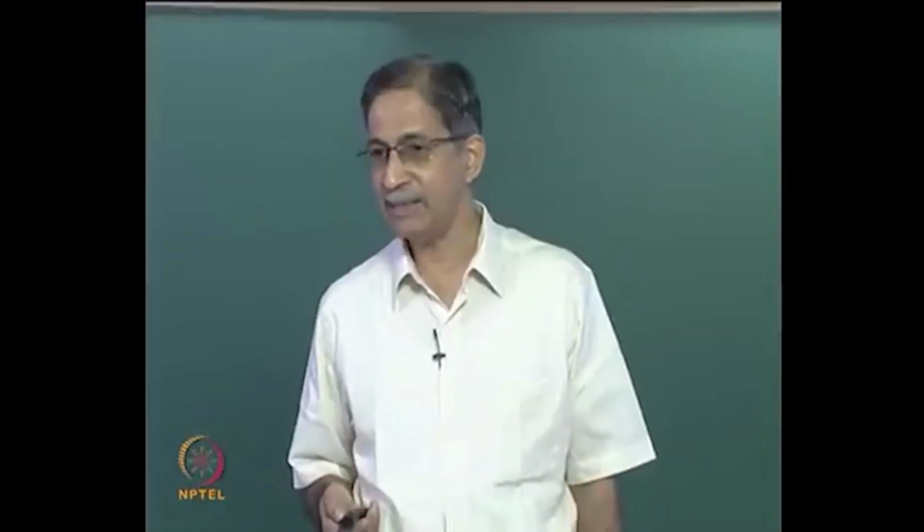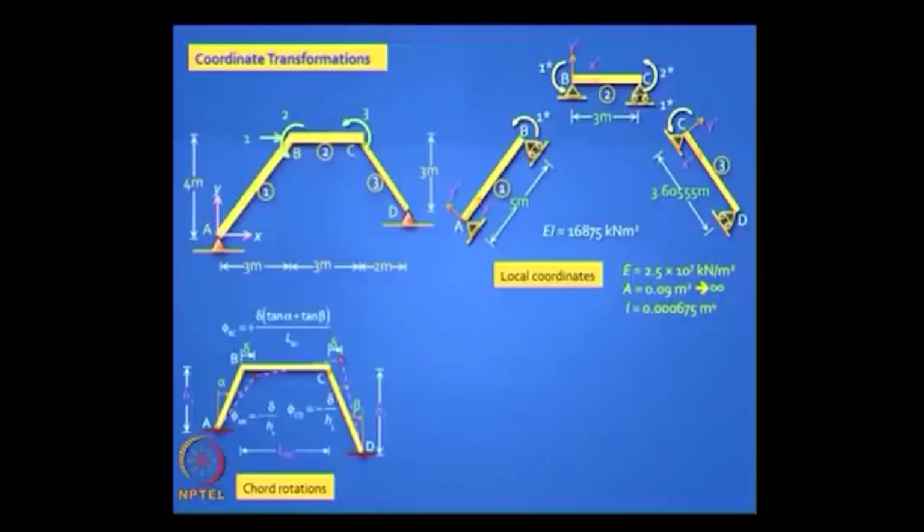I first need to write down my TD matrix, TDA matrix. Will you try that? Okay, to do that you have to be very careful. When you are dealing with sloping legs, you have to correctly express the chord rotations in terms of the sway. So the displacement D1 corresponds to the delta in this figure, right? The figure at the bottom is a generic figure.